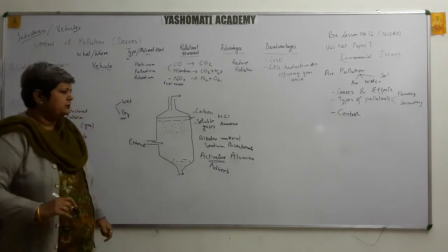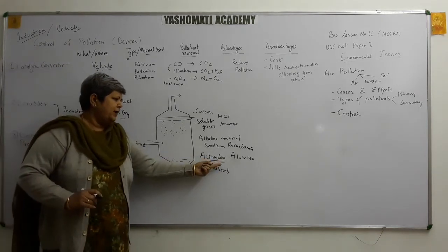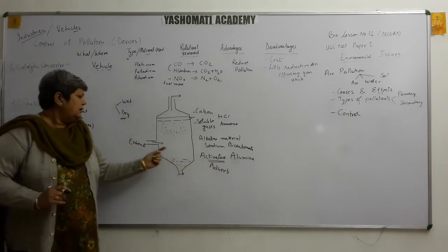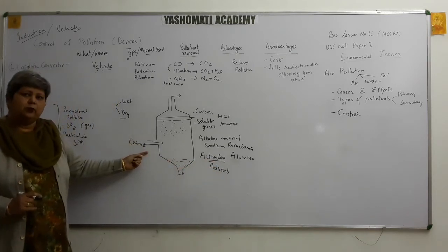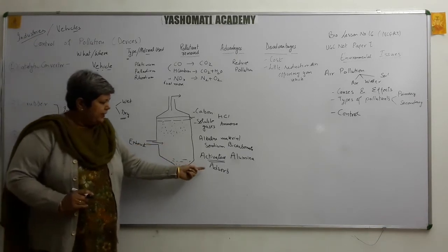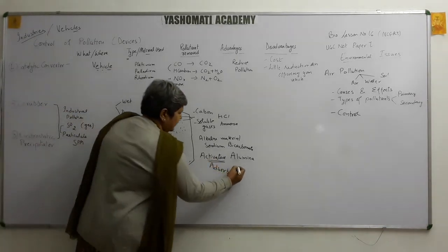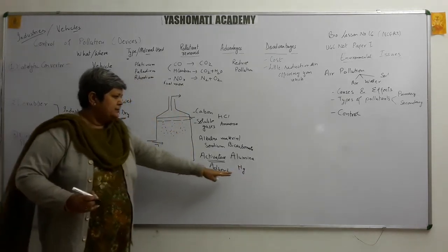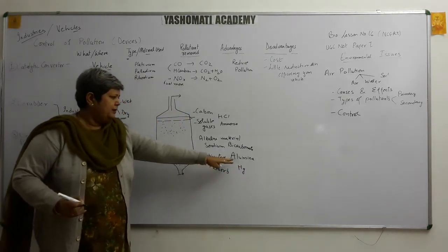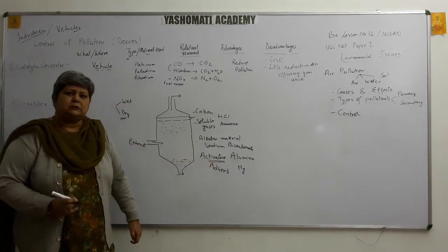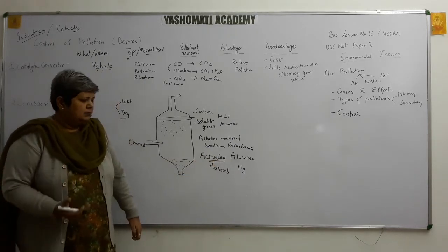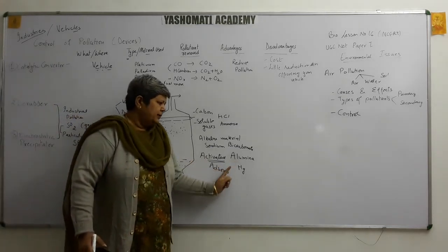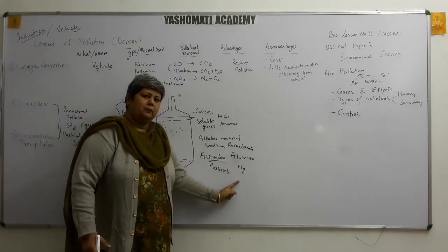some material on it. So, the choice of activated material will depend upon the kind of pollutant that we want to remove. For example, in case of mercury dust, it can be removed if we activate the alumina by halogens, maybe chloride, bromide and iodides, such type of substances. If it is activated, then even the heavy metal can be removed.